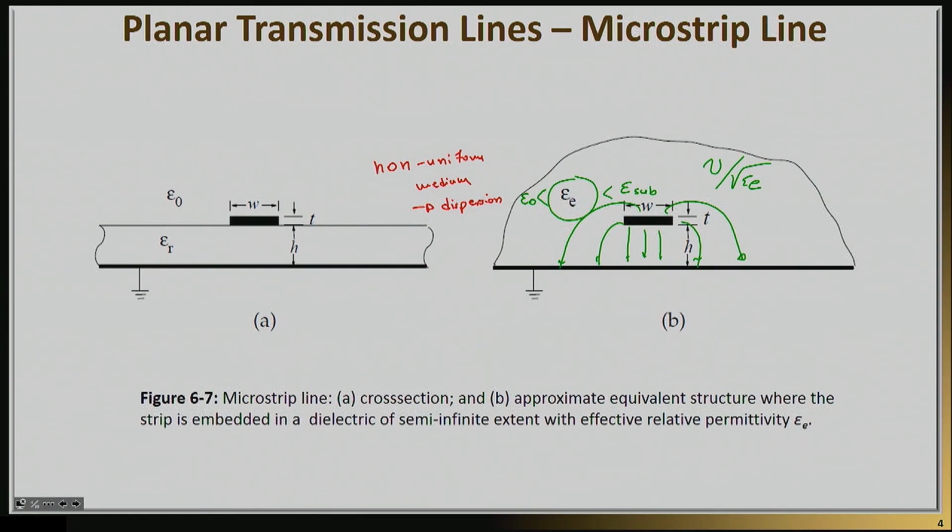And that means now that if you make a pulse at the beginning of the line and this pulse propagates through the line, this pulse obviously contains multiple frequencies, and for that reason at the end of the line there will actually be dispersion, which means that the pulse will actually be wider. And so why is that an issue? Well, that's an issue because you're not really sending one pulse.